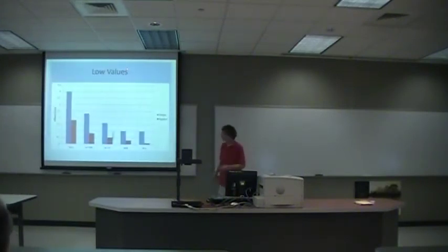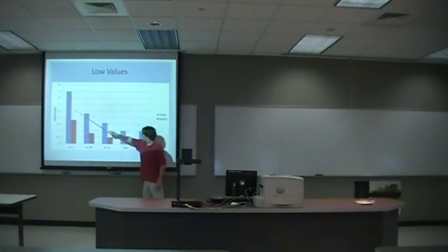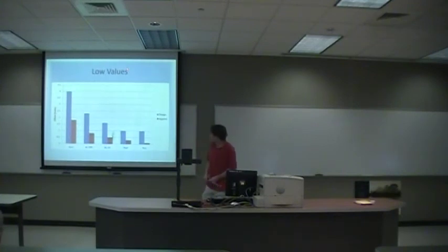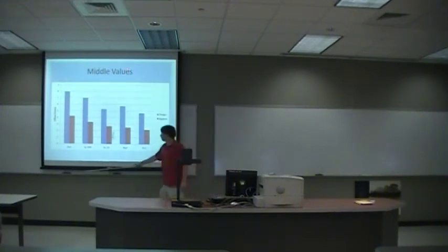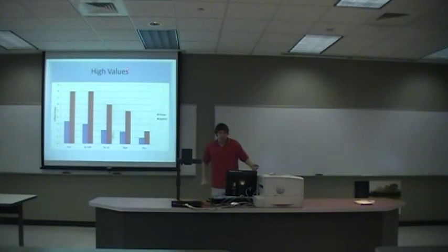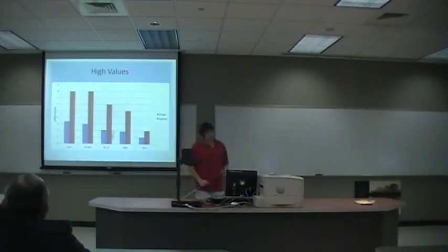As far as the low values, this is the design versus when it's actually applied. So with the low values right here, the offset for the design is a little bit higher than the actual applied. It's not twice as high in most instances. It's about the same as far as our critical damping, 500 decay, 10 decay, quarter decay, ultimate controller gain. And what's interesting was with the higher values, the actual application values are higher than the design criteria, which is kind of interesting about the system.